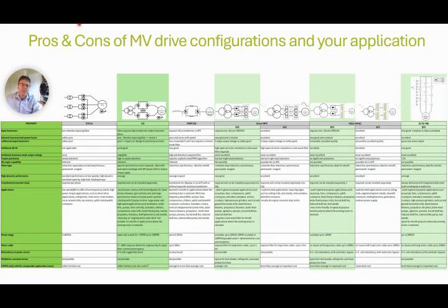Let's take a look at the output harmonics of our medium voltage drives. PWM CSI, the MMC multi-modular level, and the 2-level series Cascaded H-bridge excel in sinusoidal output voltage, making them ideal for retrofitting or reusing the existing direct online motor. The drives with direct front-end in-feed can deliver a multi-level output voltage that is relatively clean of harmonic content. The Cycloconverter and the load commutated inverter deliver poor output waveforms, requiring special attention. The LCI will need a dedicated synchronous motor.